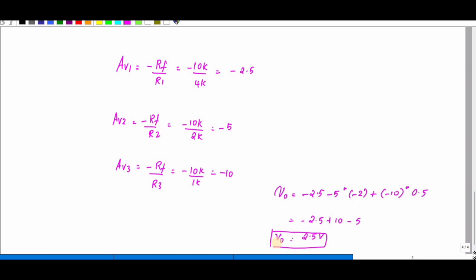The summing amplifier is also used as a level shifter. For the level shifter, one input should be an AC signal and the other one a DC signal. The proper selection of the DC value lets you place the AC signal at a desired DC offset.